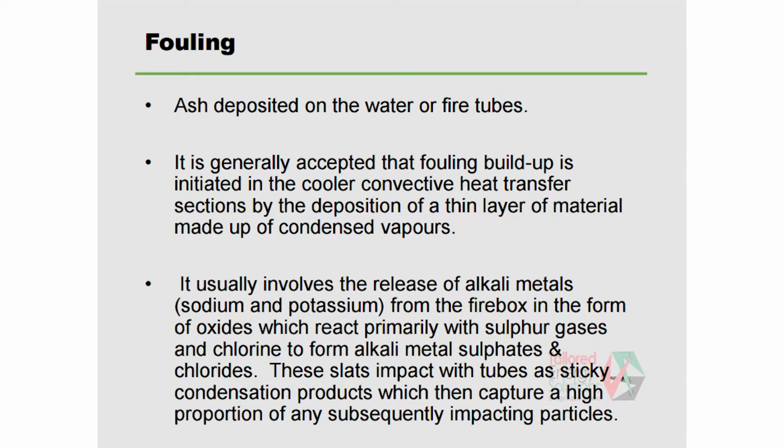Even yesterday, I was arranging a meeting where they complained, oh, I got so much clinker. So when I put my analyzer into this boiler for only about half an hour, I found your oxygen was down to 2%. The clinker is black in color because the heat is not being pushed away from the grate, with not enough excess air. To manage the clean surface, soot blowing and a proper match design between the boiler and the fuel are needed.